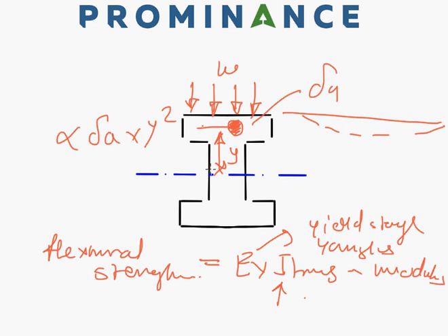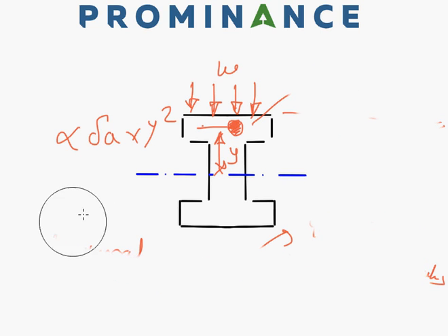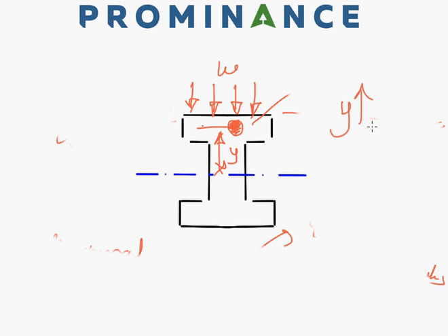So now this is pretty obvious that when your y is larger, then obviously your I will be on the higher side, and since E is a material property, the EI value, or the flexural strength, increases only with the increase of the I value for the same material.